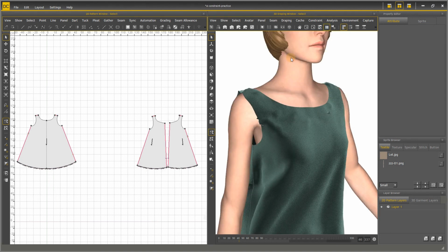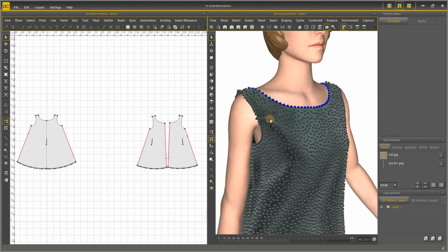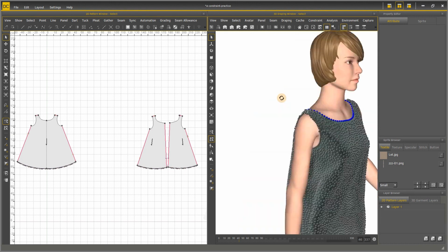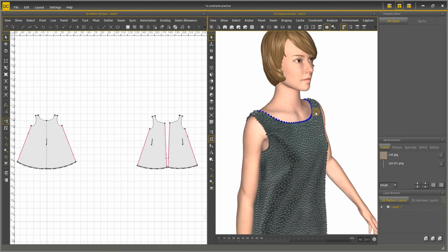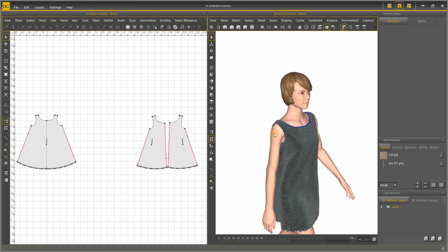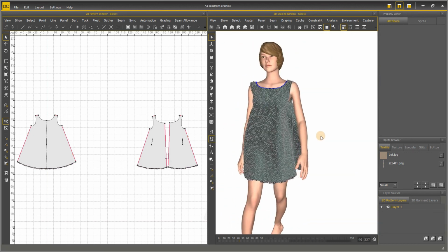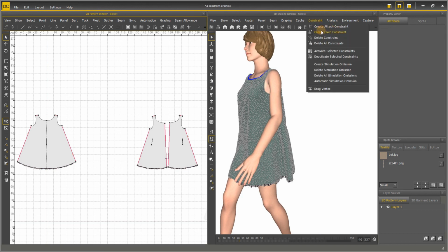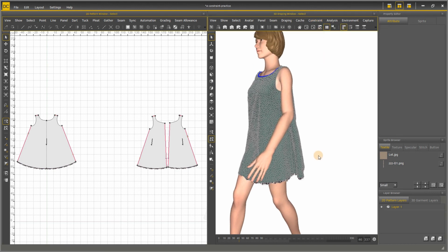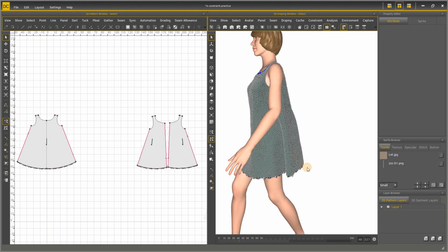When clicking to Vertex Selection mode, the blue vertices show the attach constraint I have just created. Another function similar to attach constraint is the fix constraint. It is also in the constraint menu, and the vertex assigned to fix constraint will be fixed in this environment.